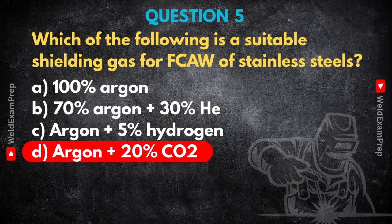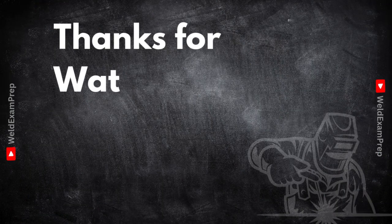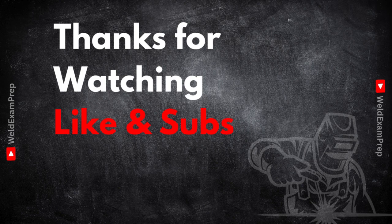Okay. And what happens if that area also has a coarse-grained, low-toughness HAZ because maybe the preheat wasn't quite right? You see how these factors can compound? Yeah, it creates a perfect storm for failure. Exactly. Thinking about those interactions, how one thing affects another, that's moving beyond just knowing the answers. That's developing real inspection insight. That's the goal. Keep connecting those dots.